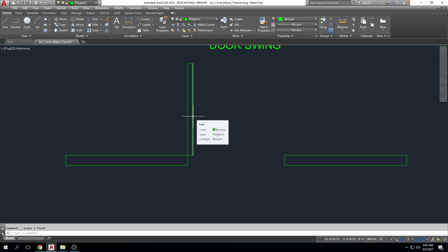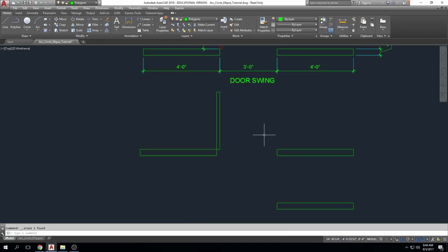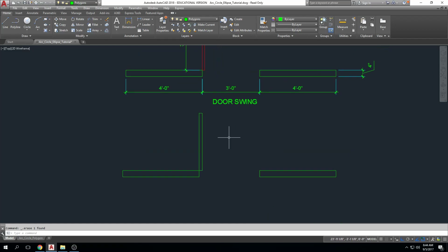It's going to be hard for you to use circles in the manner that I use them for a little while, because you won't have all the modification commands available to manipulate them. But the way that I use circles, I will use circles to draw things like door swings, right? I'll create an entire circle and then I'll trim off what I don't need, okay? Circles are used for a lot of different things, right? Furniture creation, block creation, tag creation, door swings. I use them all the time for everything, okay? Funny enough. But again, it's going to be a little bit hard for you to use circles because you don't have all the modification commands available to you yet, okay?